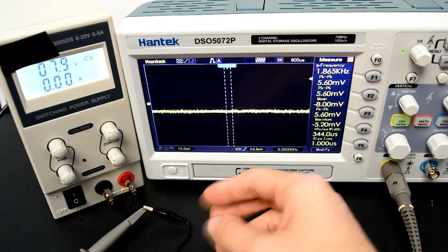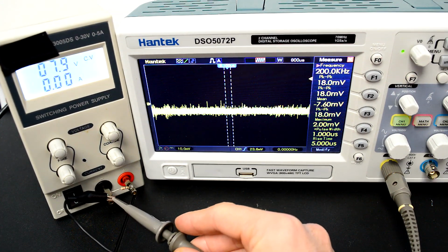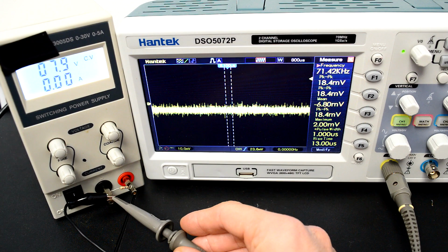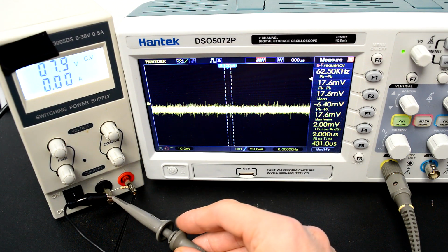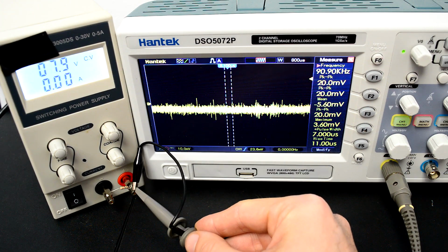Now with the final inductor added, let's just see the noise that the supply generates. We're still getting a bit of noise, but it's a bit lower, so we went from around 30 millivolts down to around 20 millivolts. So this common mode choke did actually help, and we're getting the same thing on both outputs. So in the end I managed to reduce the noise of the power supply quite substantially just by having some very simple measures. And this is all thanks to properly modeling and understanding where the noise is coming from.